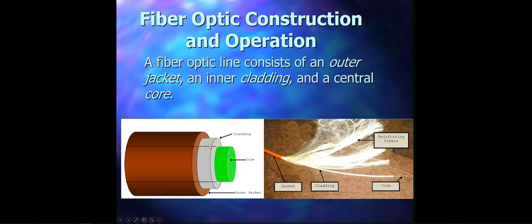The cladding surrounds the inner core, and the two components function together to carry the light wave down the fiber. The core's purpose is to carry the light, and it can be made of either transparent plastic or glass. The highest performing fibers use a glass core, which provides much lower losses and wider bandwidth. If you don't have the cladding, some of the light would escape the core on the way down the cable, resulting in signal losses.